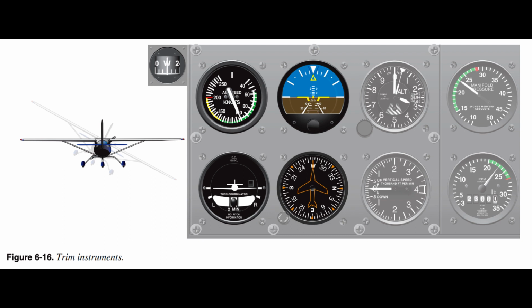Helicopter trim. A helicopter is placed in trim by continually cross-checking the instruments and performing the following. 1. Using the cyclic centering button. If the helicopter is so equipped, this relieves all possible cyclic pressures. 2. Using the pedal adjustment to center the ball of the turn indicator.